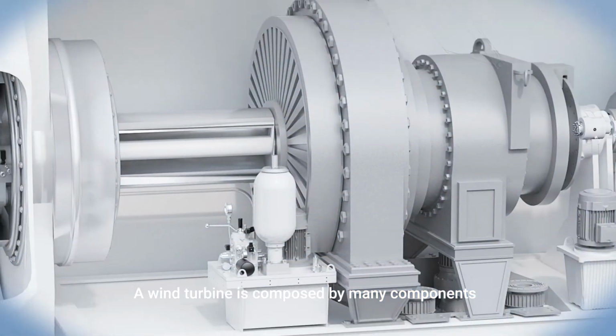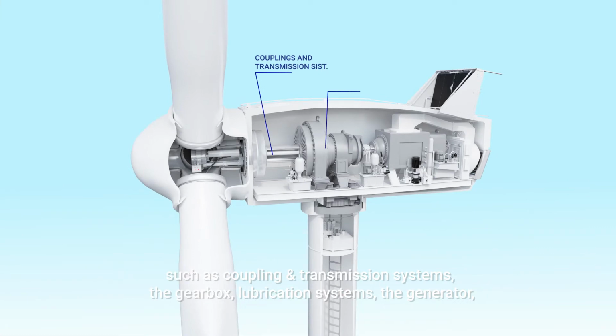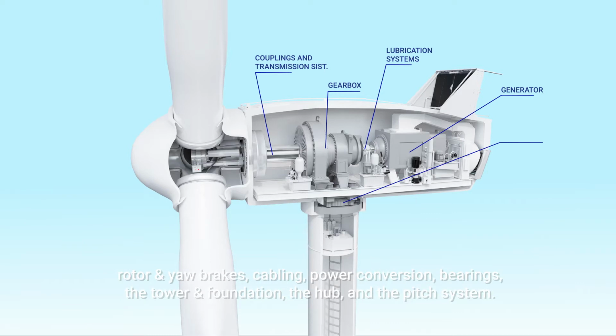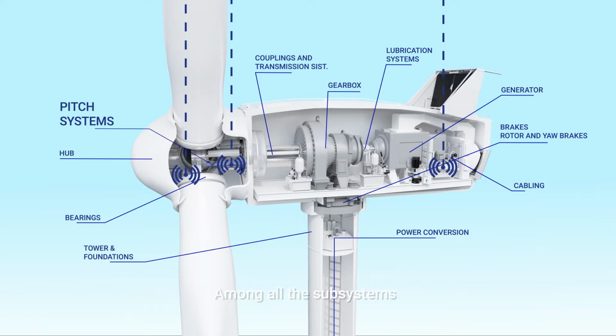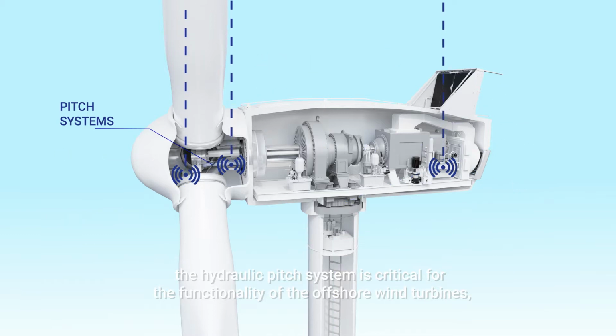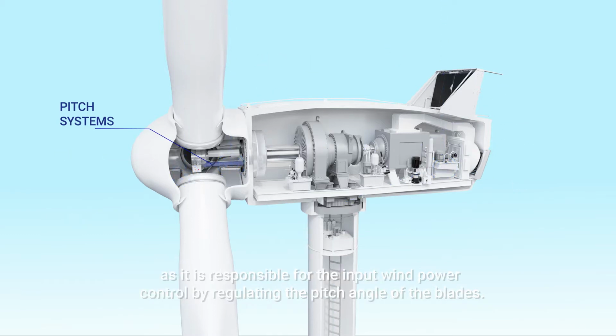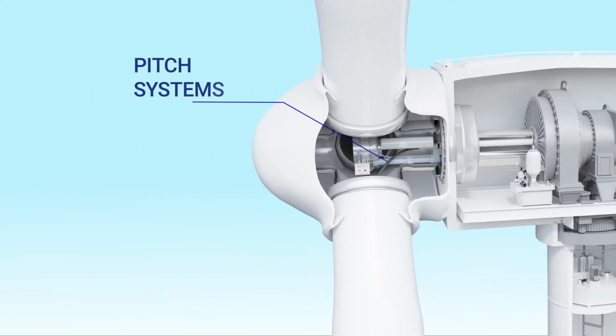A wind turbine is composed of many components, such as coupling and transmission systems, the gearbox, lubrication systems, the generator, rotor and yaw brakes, cabling, power conversion, bearings, the tower and foundation, the hub and the pitch system. Among all the systems, the hydraulic pitch is critical for the functionality of offshore wind turbines, as it is responsible for the input wind power control by regulating the pitch angle of the blades.